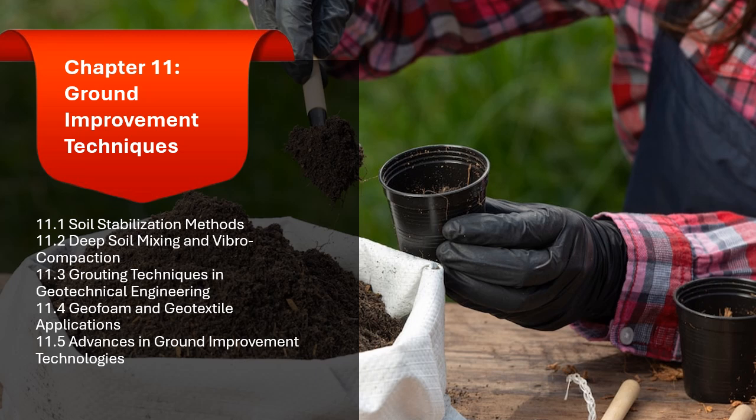2. Grout injection. The grout is injected into the ground through a series of boreholes drilled into the soil or rock. The grout is injected under controlled pressure and flow rates, ensuring even distribution throughout the target area. In some cases, a series of injection stages may be used to create overlapping grout columns or continuous grout barriers.